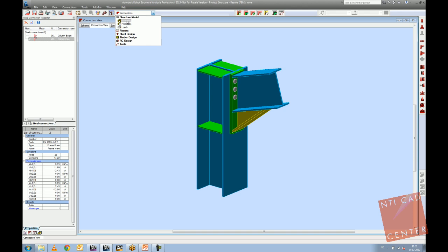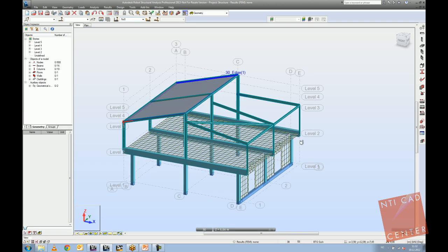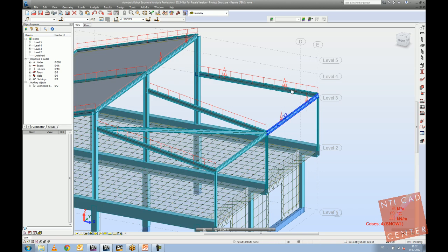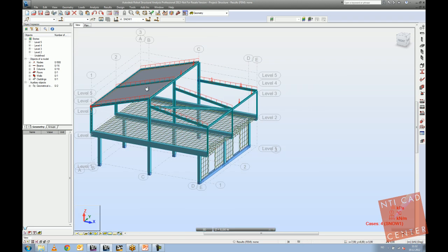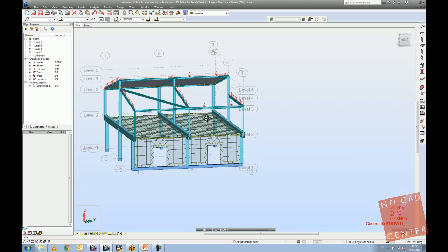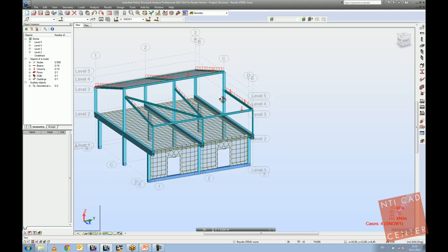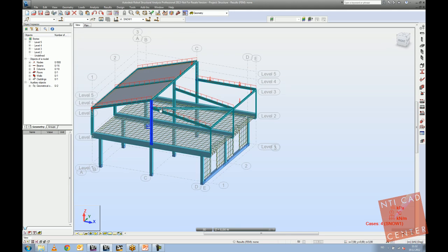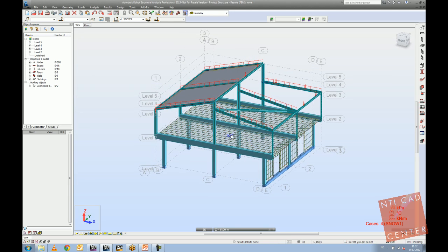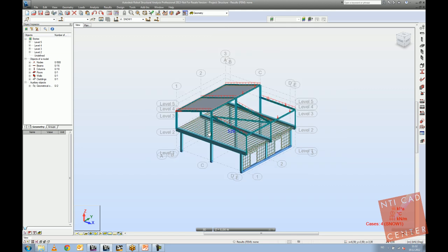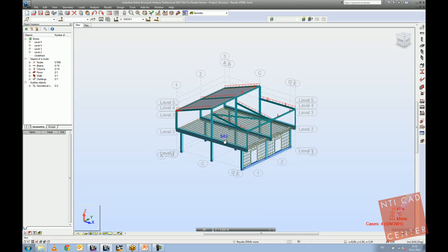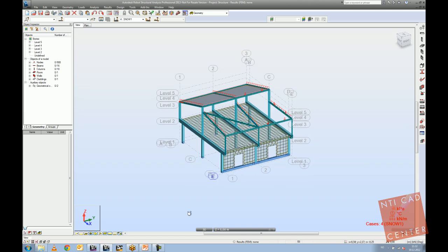If I go back to my structure geometry, and if I look at my loads, that was a snow load, I believe, you will see that I have the temperature loads I have applied. I have a cladding, and the geometry is where it was modified. So basically all of the data, even the finite element mesh, will be there because it takes the missing data from your previous integration files, which were stored there.